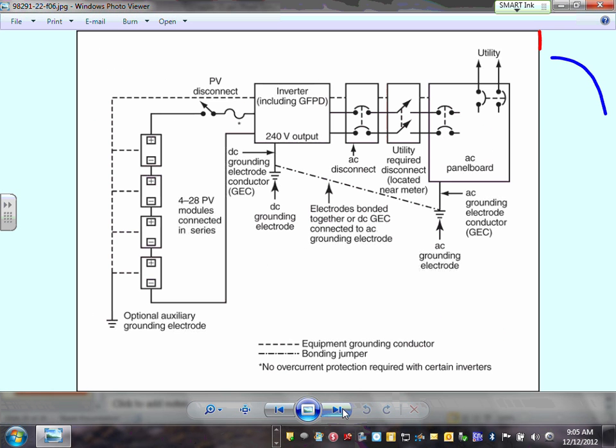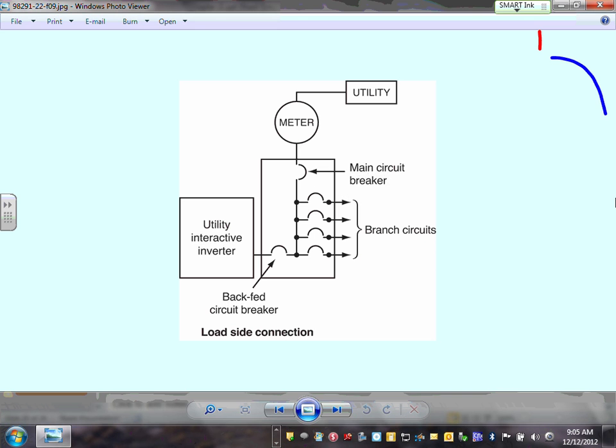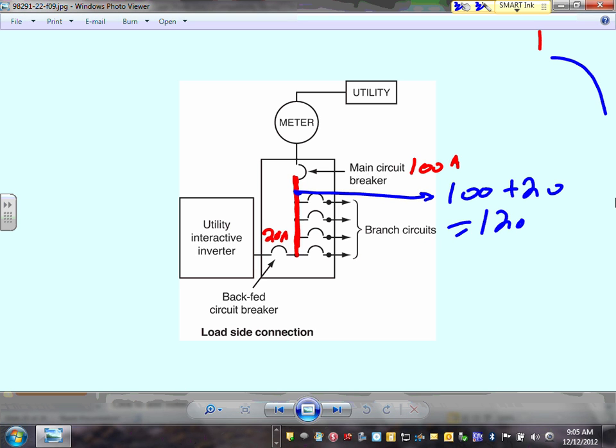A poor man's way or rich man's way. Here's the poor man's way. Like we talked about the rich man's way between the meter. The poor man's way, guys, is you tie in a disconnect at 20 amp. So you put a 20 amp as a feeder. If this is 100 amp, then the bus here, 100 amp, you cannot exceed more than, so there's a limitation though. Here's the limitation. Do you see that bus here? The size of this bus, guys, when you add 100 plus 20 equals 120 amps.